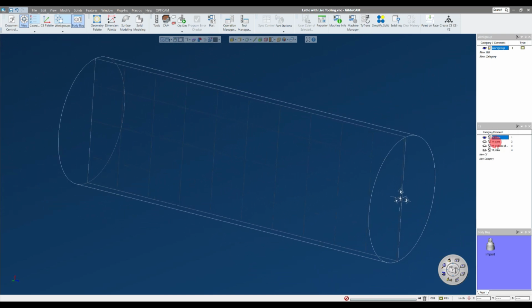So in my coordinate system list here, and again, I like to see it on the screen, but the button to turn the coordinate systems on and off, it's a two-part button. So if you use the bottom portion of the button, it has all the same functionality that you do in the palette here. And the same thing with your work groups. Work groups, some other software calls them layers, but those are different layers of the screen that you can put different layers of geometry. And we'll talk more about that in a little while. So again, at the bottom portion of that, you have all the same functionality that you do with having the palette on the screen. So whether you use the bottom portion of the button or use the top portion to turn it on or off, totally up to you, no right or wrong.